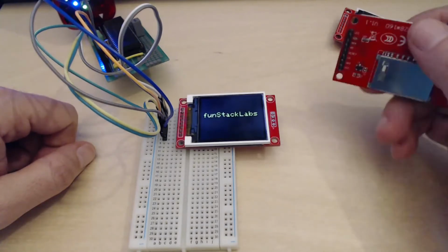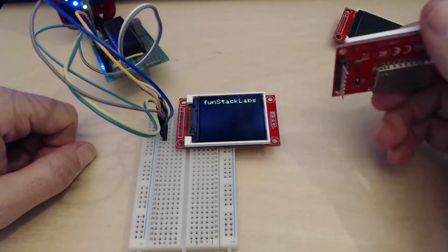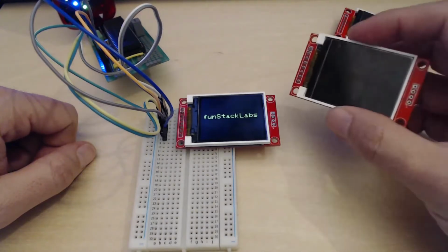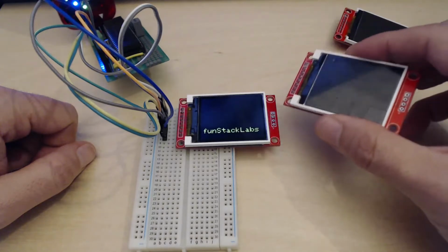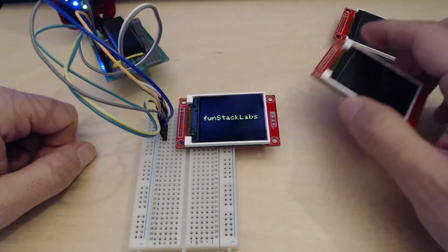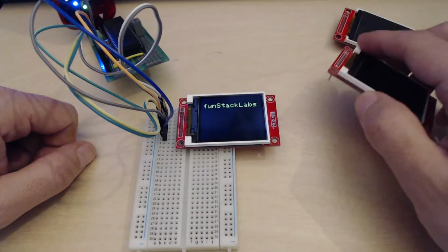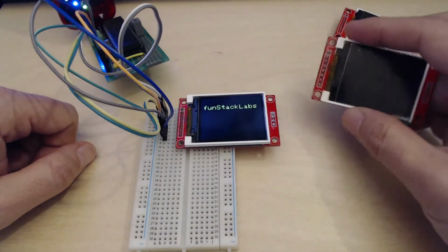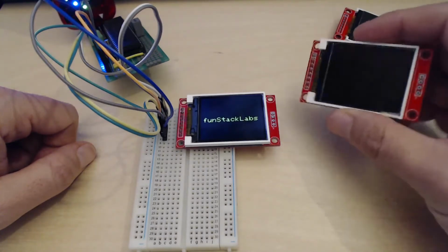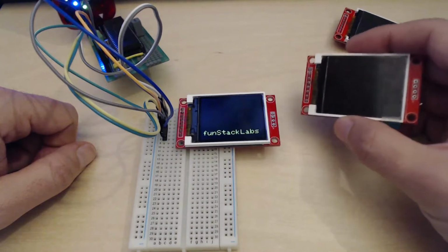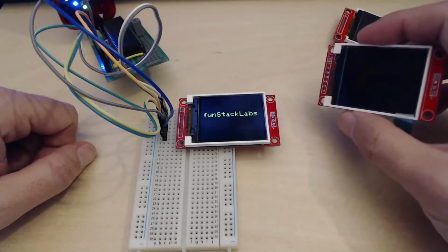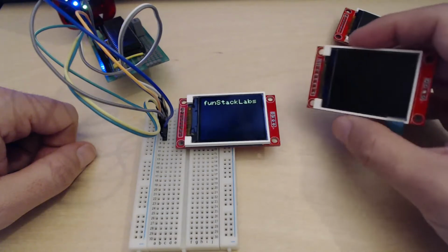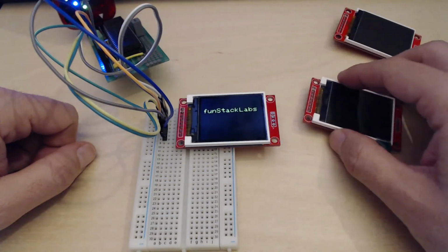So, you have a great project. Now you just want to add some graphic display to it. I recommend you choose a graphic display in the early stages of your project, so it makes everything easier when you're designing the power and understanding the power requirements of your project. You can put one on later down the track, but it's easier design-wise if you pick a display first, and then design the rest of your circuit.